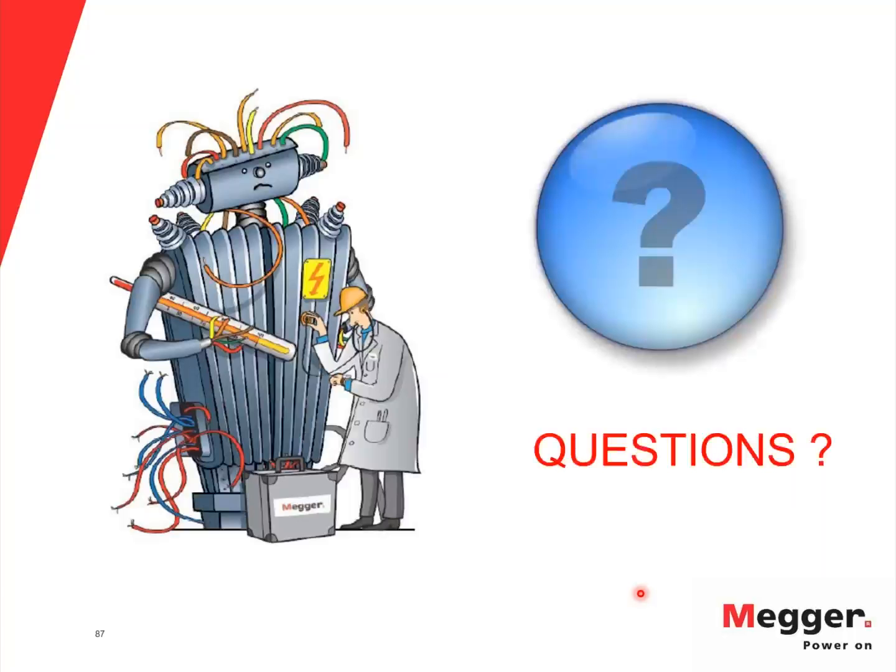First question is going to be for our panelist, Diego. During testing, should all tap positions be tested? Good morning, everyone. One of the typical questions will be if I have to test all the taps or not. The first question that we need to ask really is, what kind of testing are you performing? Is this a commissioning testing? Is it factory acceptance testing? If that is the case and you're commissioning and you're doing the acceptance testing in the factory, then I would prefer to test every single tap available in my transformer.